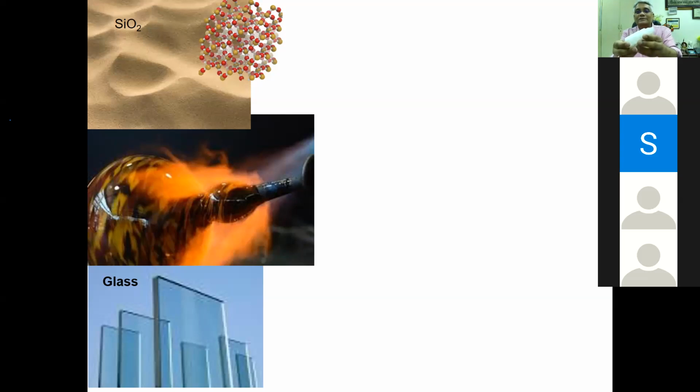Actually, you see, this is the naturally formed crystal. This plane is an identifiable plane. So that means it has a cleavable crystallographic axis along that plane. And since that kind of directionality is not there in the case of glassy material, sometimes glassy materials can be more strong. You understand? Yes, sir.